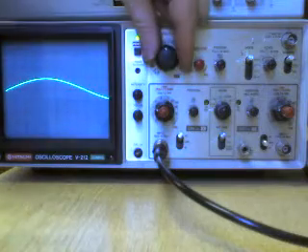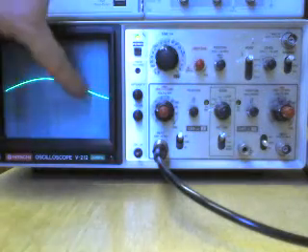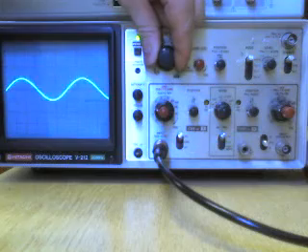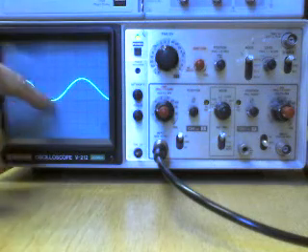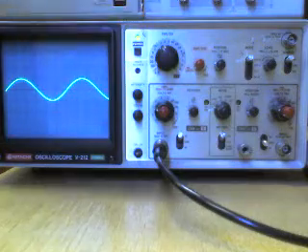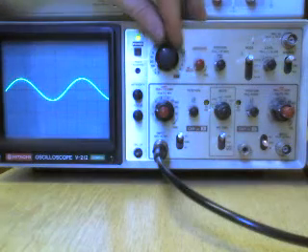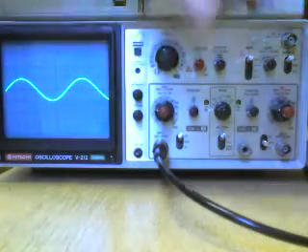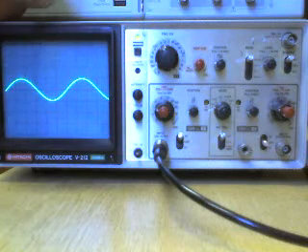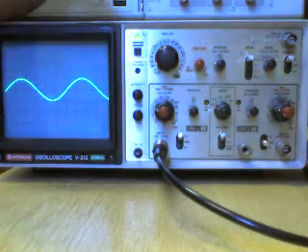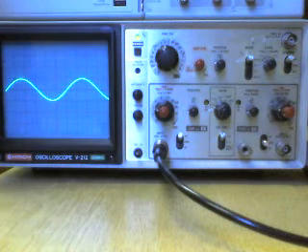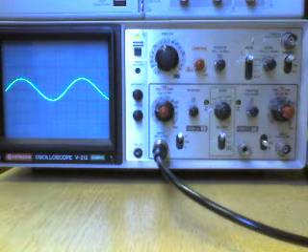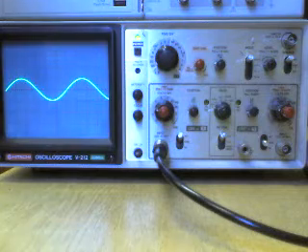Now then, first thing that we do, we can see our positives on this side, so let's change our time so we can actually see some waves on the screen. There we go, we can see a full wave on the screen. Okay, now on an oscilloscope it's always best to view the signal as big as possible. Okay, so it means fiddling about with your controls, your volts per division and your time per division, just like measuring on a graph. Okay, the larger your graph, the more increments that you can put on your graph. That means the more accurately you can measure your trace on your graph. It's exactly the same thing with an oscilloscope screen.